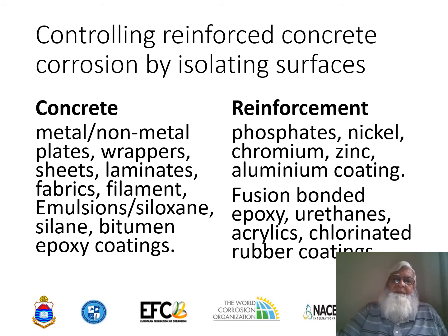For the reinforcements, apply coatings like phosphorus coatings, nickel, chromium, zinc coatings, and aluminium coatings. They're all applied by chemical means or by thermal means, right? And they form a thin layer of these coatings which are more corrosion resistant than the steel and can isolate the steel surface from the environment.